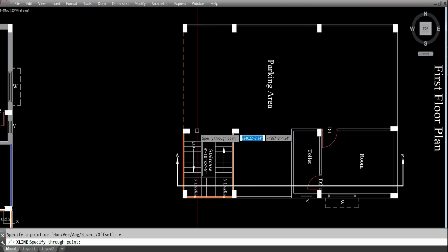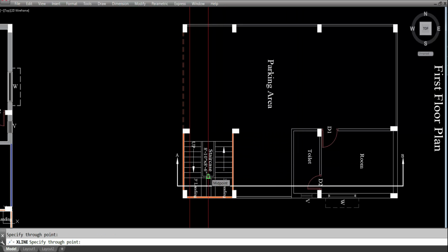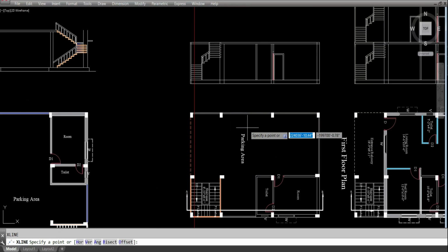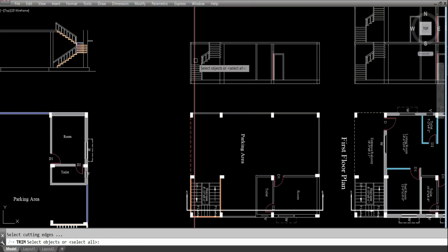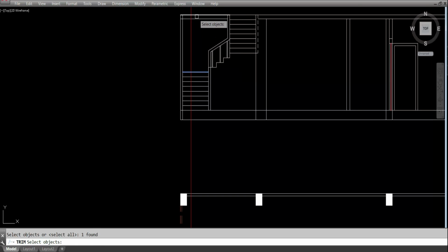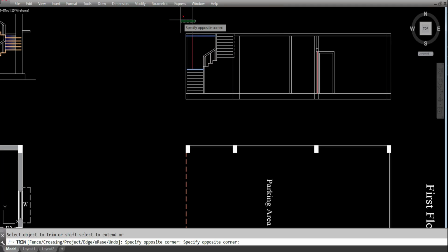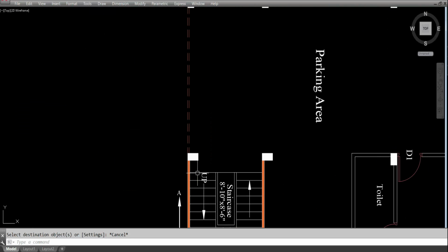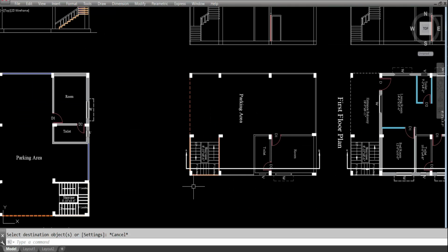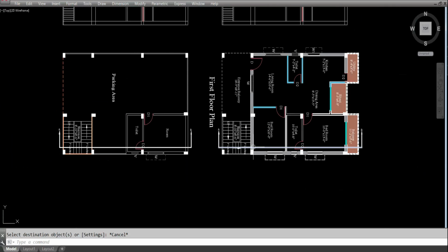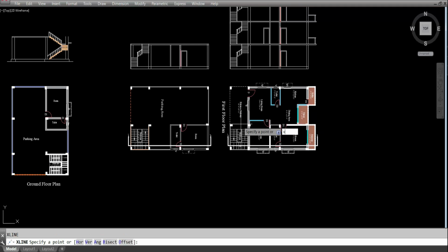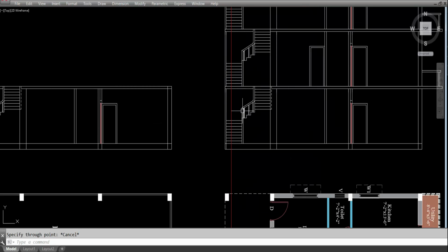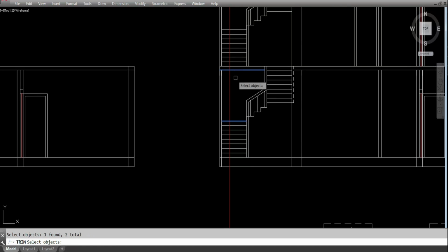Now, construction line, vertical line. Take construction line from here, projection line of this column. Here also we can see the column. Okay. First, staircase will be there, staircase elevation, and till this level we can see the column. Column will be there as the column stays, but we can see till this, because in front of column staircase will be there. Okay. Now XL, enter. Here also we have to provide column. Okay. Trim, we have to trim.